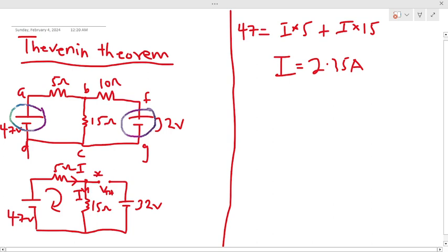We said that for us to use Thevenin's theorem, we should find the Thevenin's voltage and the Thevenin's resistance. Now this current that we found is going to help us find the Thevenin's voltage. For the Thevenin's voltage, we choose this direction to be positive. You can choose any direction, but you should make sure that your sign convention is really good. I will put the link to the Kirchhoff's voltage law video for you to watch so that you get to understand how we get our sign conventions.